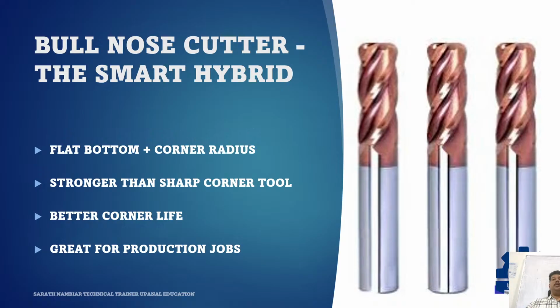Because sharp corners are weak stress points. During heavy cuts or vibrations, corners can chip fast. By adding radius, tool strength improves, tool life often improves, surface transition improves, confidence improves. This is why many experienced people love bullnose cutters. They are practical, they are durable, they are productive.